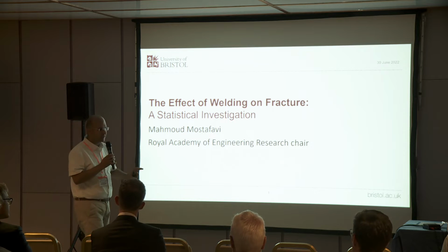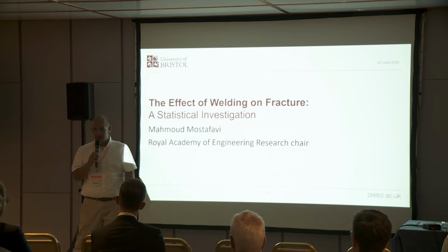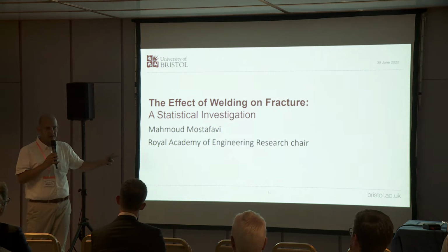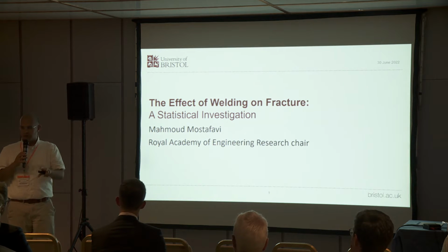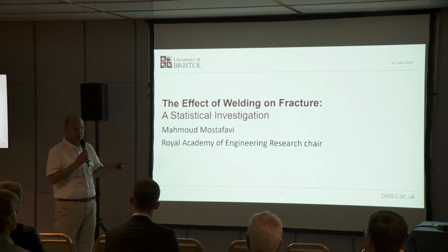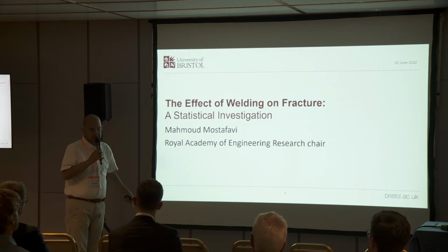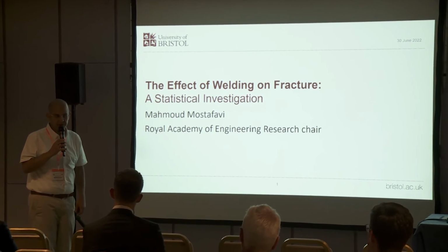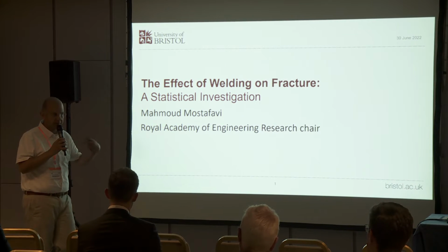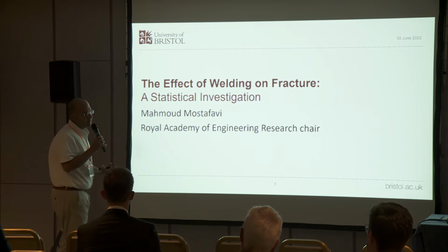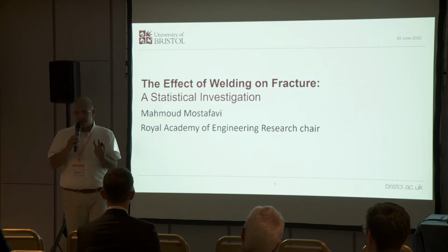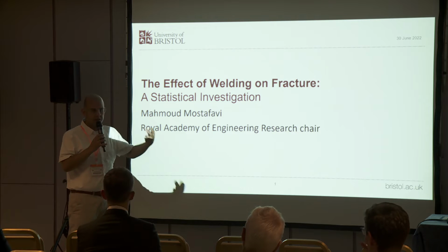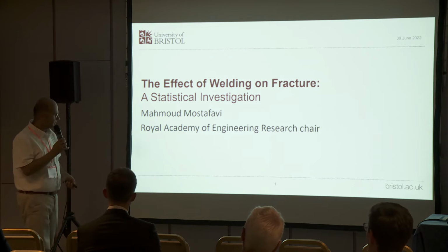If we look at the lower bound fracture of welds, we end up closing power plants that are safe to run, and therefore it's more desirable that we work towards a probabilistic approach and then do a risk-benefit analysis. Can you live with a weld maybe breaking 0.1%? If you can, probably you can extend the life of that thing. But a probabilistic assessment means you have to look at the variation in everything, variation in residual stress, variation in fracture toughness. You have to do a lot of sensitivity analysis for all of these.